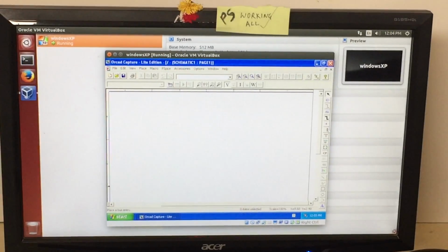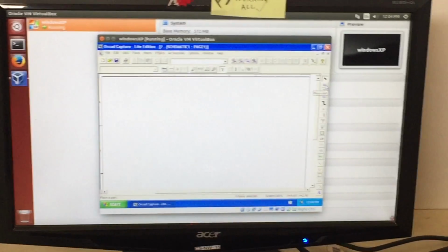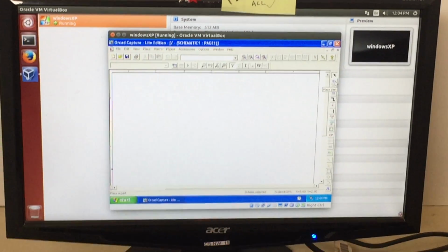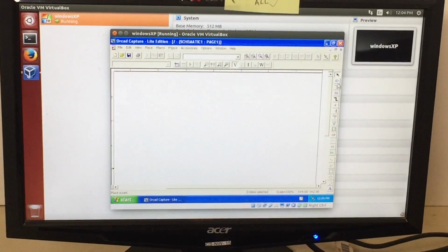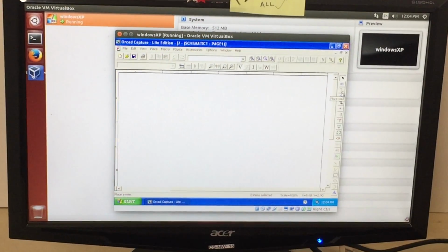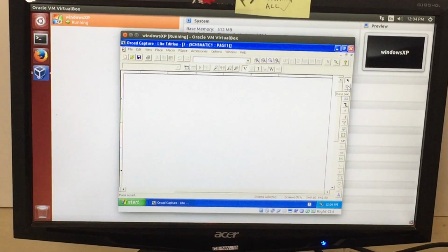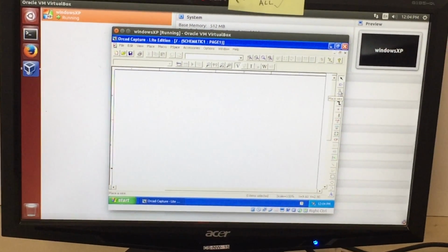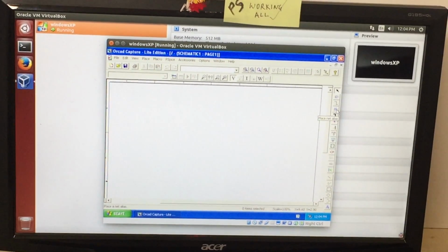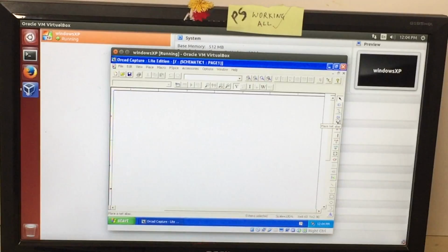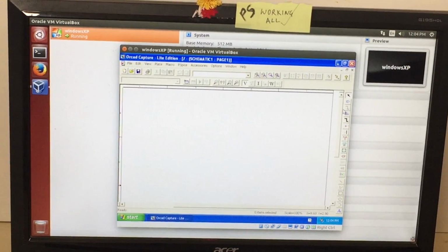Understanding? So now here all the toolbars are there, which is very user friendly. Whenever you go near one, you will get a small description of it. But here you are not using anything else, only place a part. Can you observe here? Place a part is for selecting all the components. Place a wire is for connecting them. And N1 is there. Can you observe here? Yes or no? Yes, miss. N1 is for connecting the ground. I'll tell you where to do it.